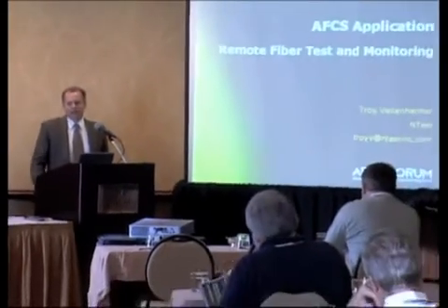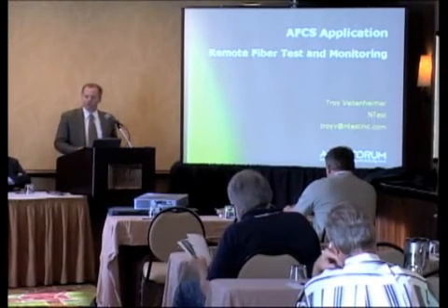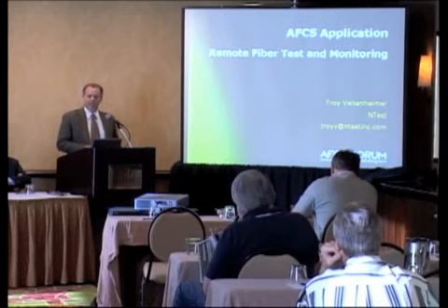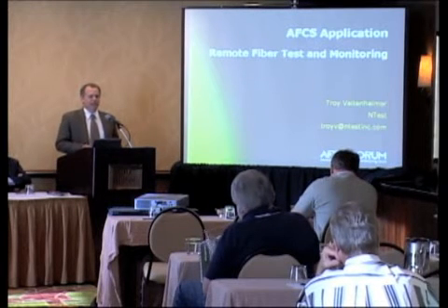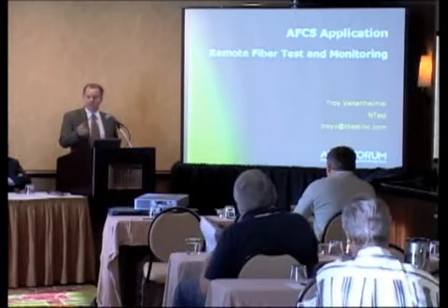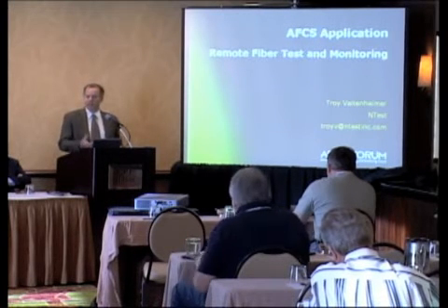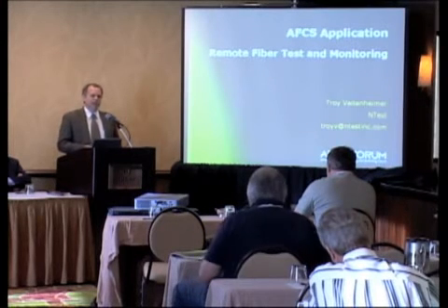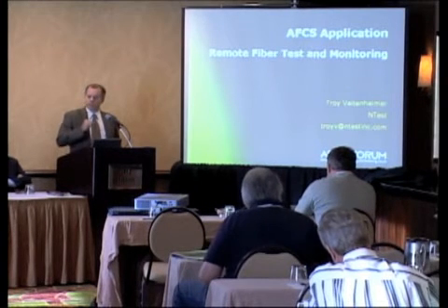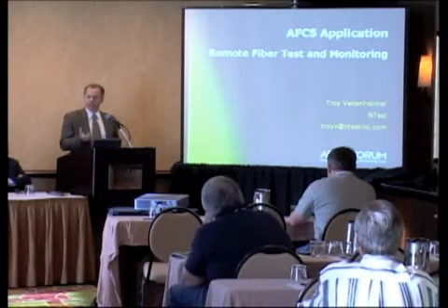Again, the company that I represent is NTest, and my topic is remote fiber test systems and monitoring systems. For people not familiar with remote fiber test systems, it's a server-based system in a NOC setting, and it continuously and automatically tests the physical fiber. When we were talking about the breaks or the cuts or attenuation that may be introduced into a network, the system continuously monitors that by using an OTDR, which, when the system is first installed or running properly, sends a trace and saves that trace.